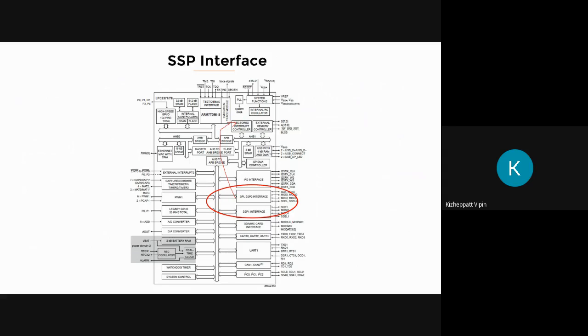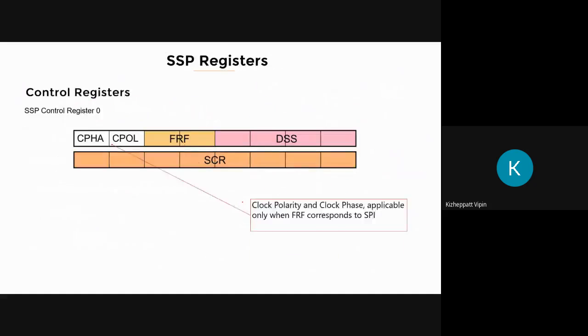While I am processing one interrupt, I don't want to get another interrupt from the same peripheral, so we usually disable it for that time. After that, we will re-enable it. But it is possible that while I was running the interrupt service routine, the same peripheral had an issue and raised an interrupt, but it was masked. So after the ISR, I can read this raw status and find it out.